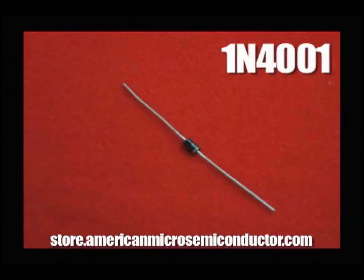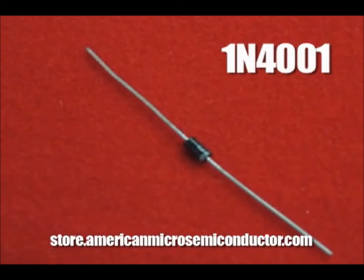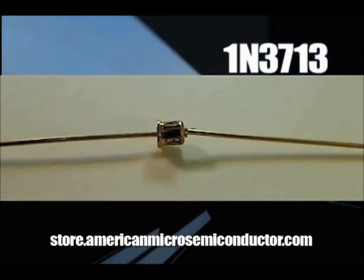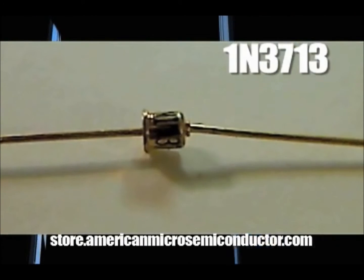On the left is the standard 1N4001 diode that can be purchased at American Micro Semiconductor. This diode will have conventional PN junction characteristics and was made with standard and conventional processing techniques. On the right side, we're going to look at a 1N3713 tunnel diode. Here the junction is made in a non-conventional method. We're taking a look at a diode that is extremely heavily doped with impurities. Lots of metallization is put on the junction.